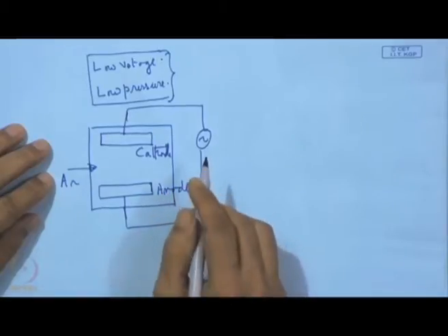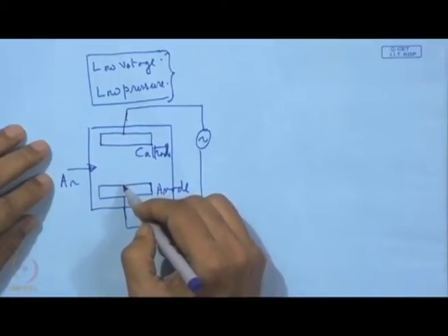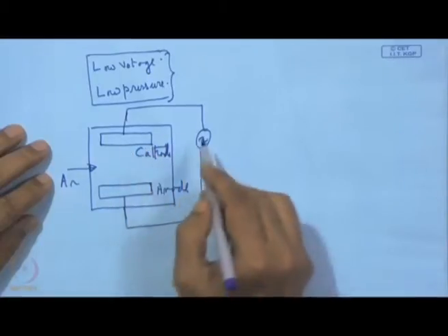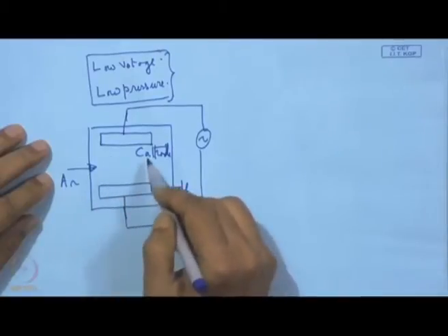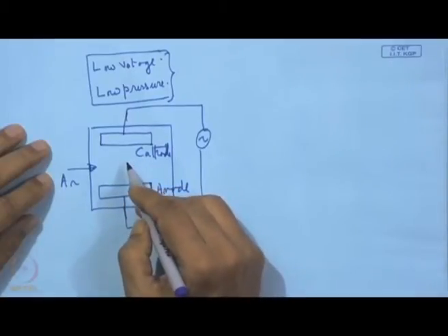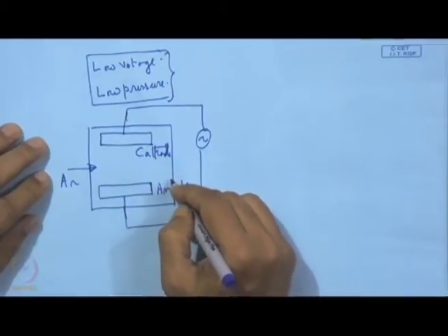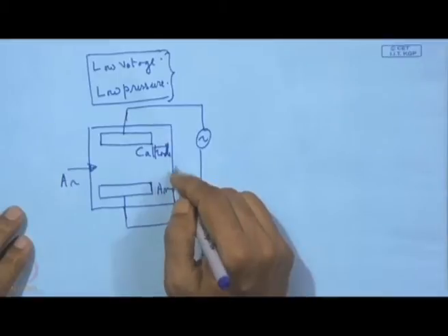What is important here is that the secondary electrons that emerge from the cathode, had it been DC, will be pulled into this plasma volume where they become primary electrons, and with collision or even without any collision they can strike the anode surface and get lost.